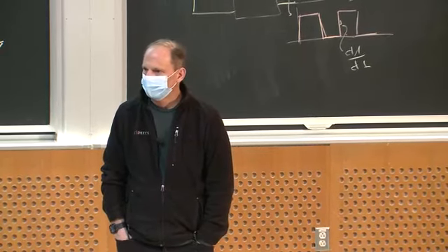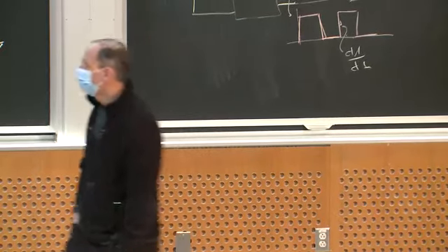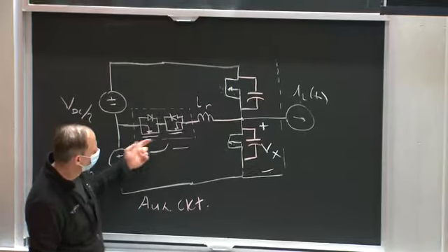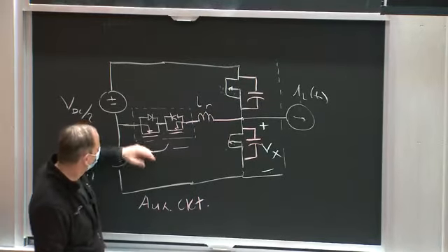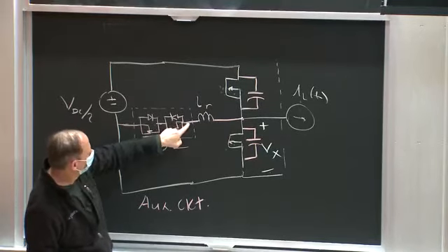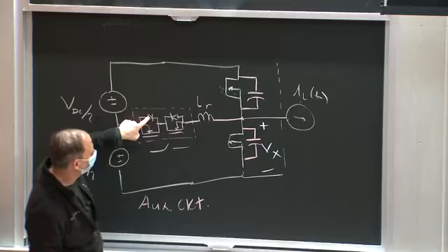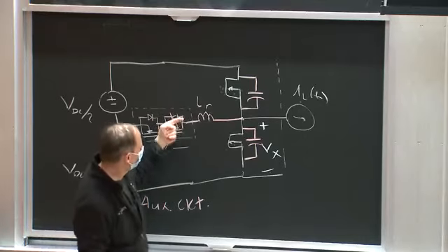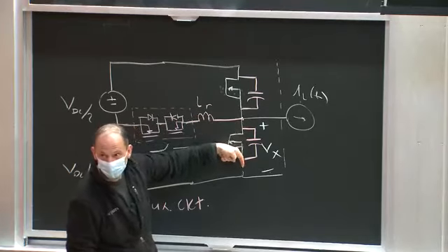So abruptly turn off the current in the LR? Well, you don't. What you do is, suppose you're going from bottom to top. If I turn this switch on and leave this switch off, this diode conducts. I will charge current positively in LR.